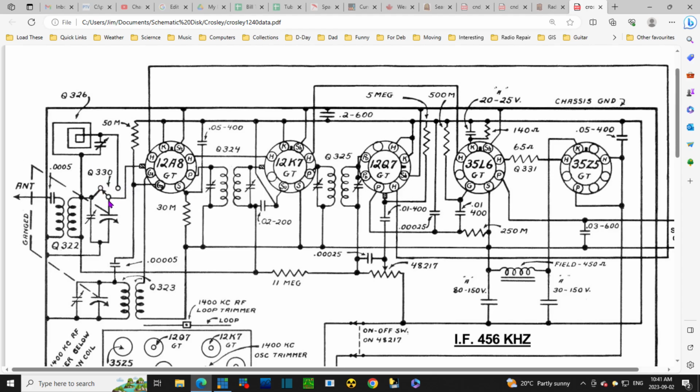Oh my gosh, you're switching from taking the signal out of the antenna, which I believe is how it's connected, to taking the signal, I guess essentially from this wire through the transformer. So the transformer is not doing much when you're utilizing the loop antenna. And the AVC voltage path, assuming again this dot is wrong, up through here.